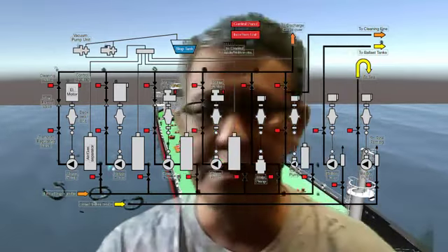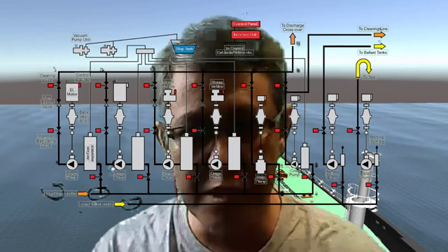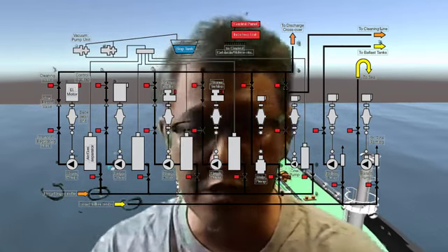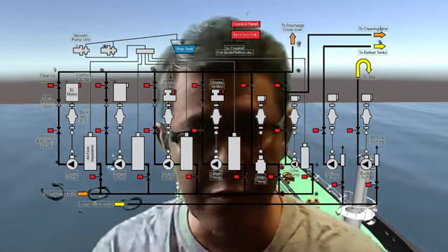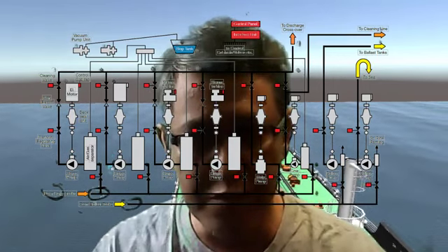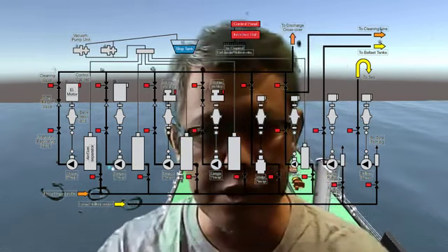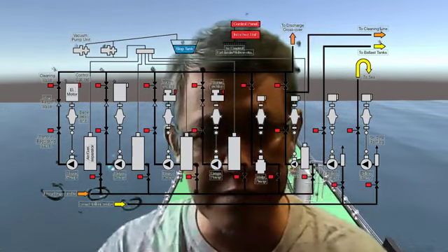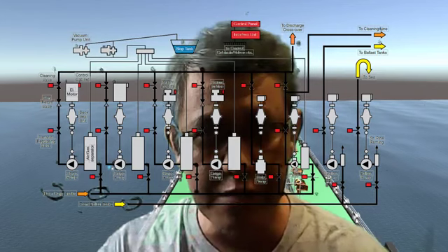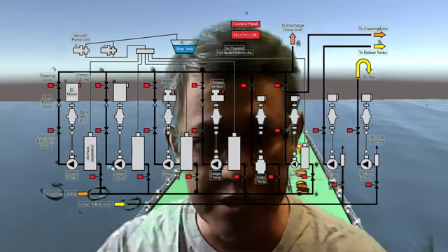which we just disregard. And of course, as I mentioned earlier, centrifugal pumps on very large crude carriers or even larger, like ultra large crude carriers, if they have a pump room, cannot actually remove all the cargo down to its draining level. In most cases, eventually it loses suction, and I have already mentioned the reason why.